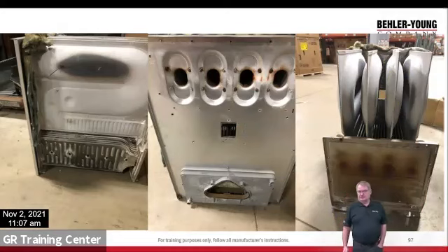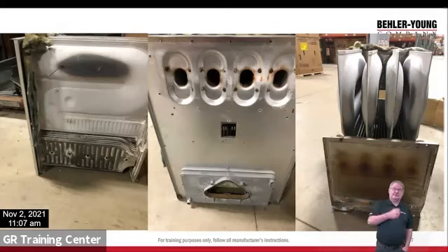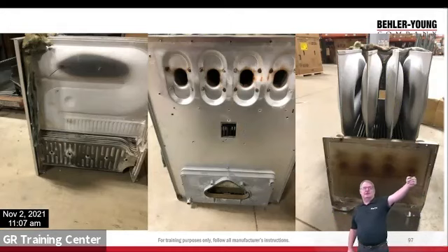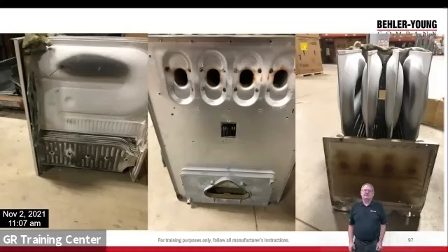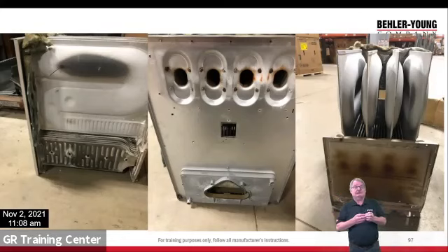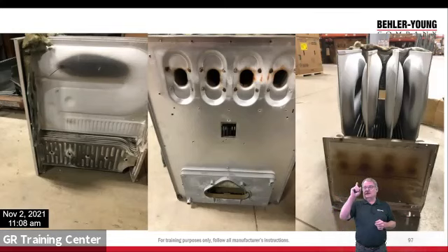So if I look, here's a 90% heat exchanger. In the picture over to the left there, you can see where the burners were at the top. You can see the discolored spot in the heat exchanger. That's where that in-shot burner flame was hitting. Or wasn't hitting the metal, but just where the most concentrated heat was. And then the fan is forcing all that flue gas through that primary heat exchanger, exchanges heat to the air. Then we're going to come out the back over my head here.